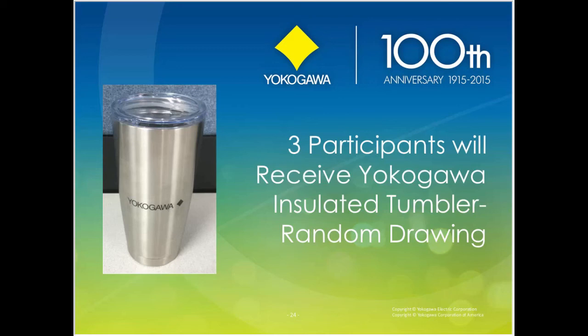Yeah, that was a good question. We got another one from Mariana Cunningham. How does Yokogawa handle the ASME PTC 19.3 thermal well calculations? Do they have a calculator that customers can use? We don't have a calculator, but if you call into our support center and give us your process information, we can either send off to get an official wake frequency calculation report, or we can do an initial one that's not official to give you an idea of whether you have that possibility of the thermal well breaking off.